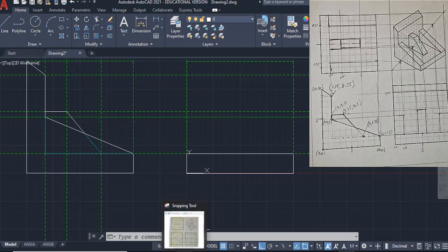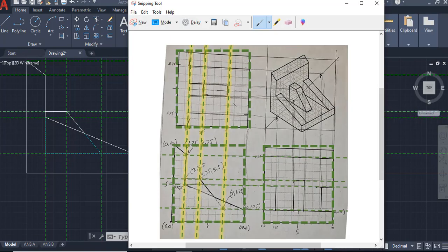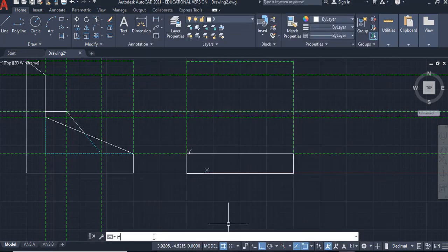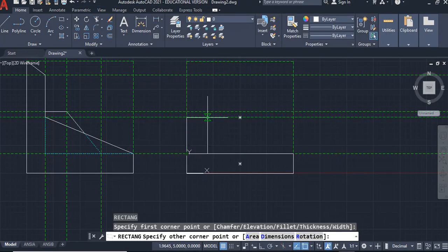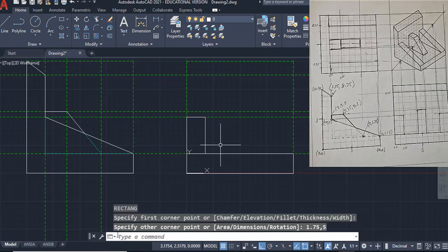Okay, so this little slab at the left, we're going to go ahead and maybe make it 1.75 long, and then try and snap it up here. So this is going to be a little bit tricky to get to the right spot. Using the coordinates down here, that will also help you to figure out what those are.